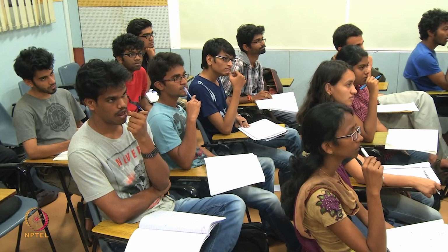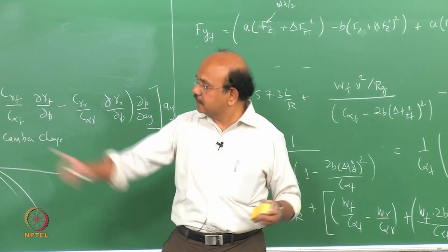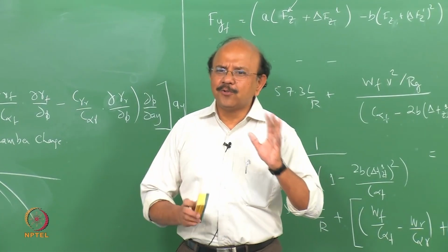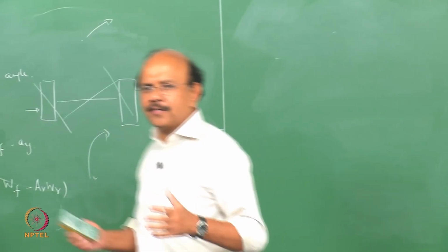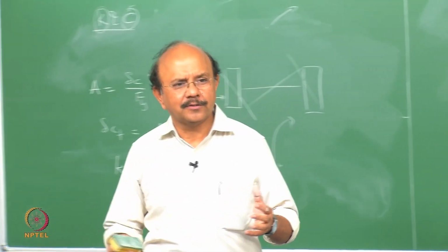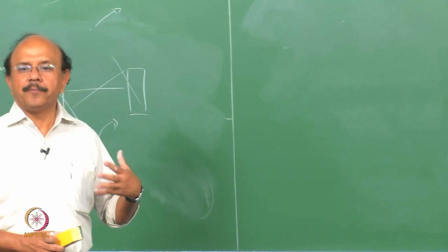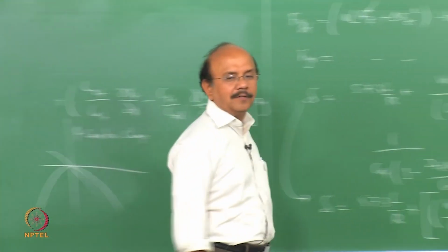No, we had talked about pull already, and where it acts is what we call lateral compliance steer. But see, this load transfer seems to be the first major thing. So what is the other thing that is going to cause load transfer? Correct. So traction or braking is going to cause load transfer.